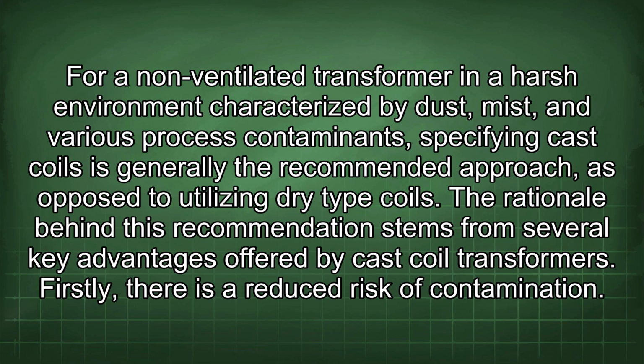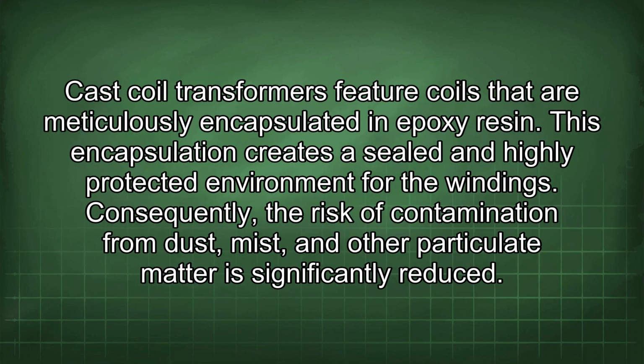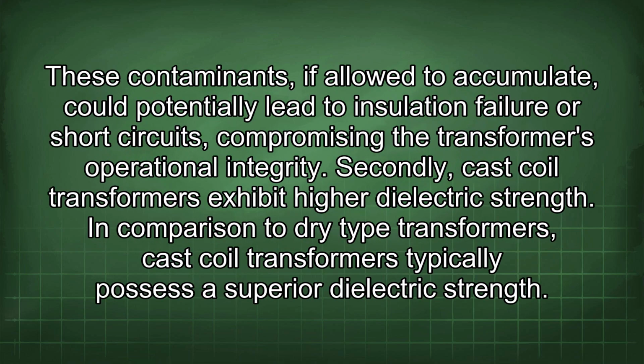Firstly, there is a reduced risk of contamination. Cast coil transformers feature coils that are meticulously encapsulated in epoxy resin. This encapsulation creates a sealed and highly protected environment for the windings. Consequently, the risk of contamination from dust, mist, and other particulate matter is significantly reduced. These contaminants, if allowed to accumulate, could potentially lead to insulation failure or short circuits, compromising the transformer's operational integrity.